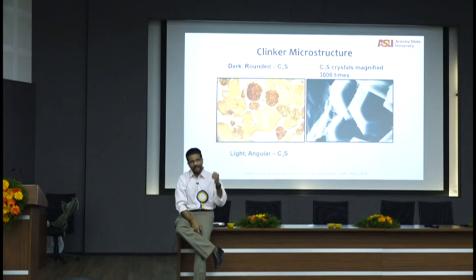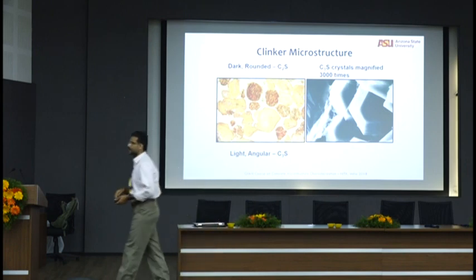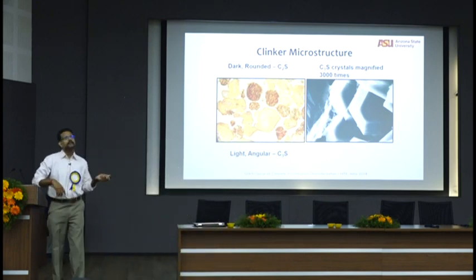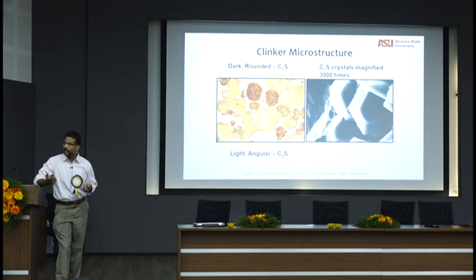Okay? So C3S being crystalline, you will get a weak crystalline peak for C3S, even though we generally classify cements as amorphous, because amorphous materials are more reactive. Crystalline materials are very stable, they don't react well. But you will have a small crystalline peak for C3S. One way of identifying the reactivity of a cement based on X-ray diffraction is to see what level of crystallinity you have in your C3S.